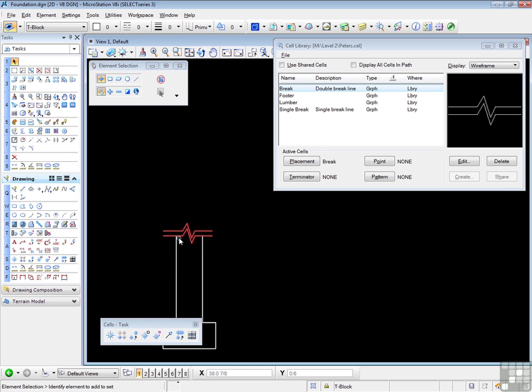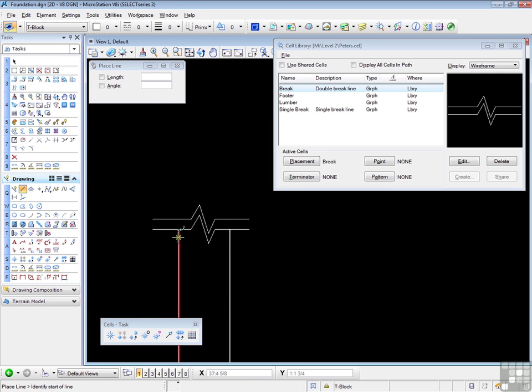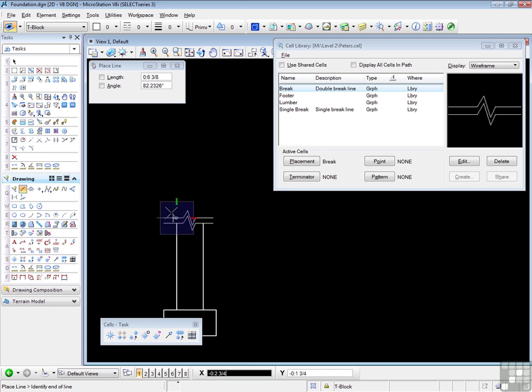Next, I need to develop the upper part of the foundation wall, which again are lines. And I need to line them up, of course, with the lower lines. So F11 again, and O for the compass. We'll go up, press Enter for Smart Lock, find that point, left click, drag upwards.